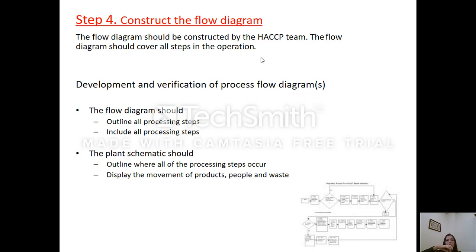After hot filling, we steam, okay, then all the jars will enter into a kind of pasteurizer, where the temperature will increase to reach about 90 degrees for almost 15 minutes, followed by a cooling step. The cooling should be at a temperature of 1 to 4. Why do we cool the product? We cool the product to avoid putting it in the danger zone. Usually we cool by spraying cold water, okay, and then after the cooling we should have a dryer to remove the residues of water.